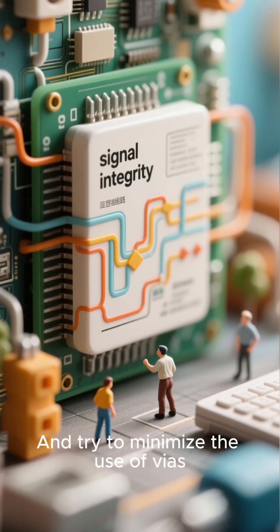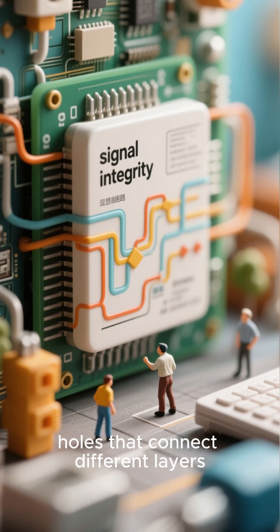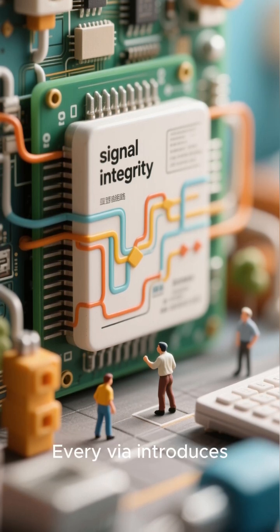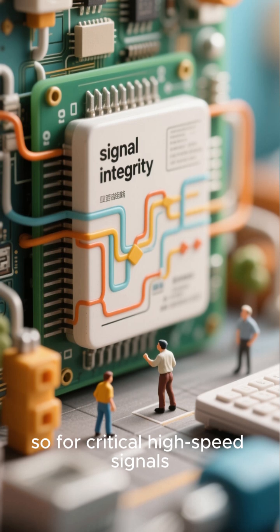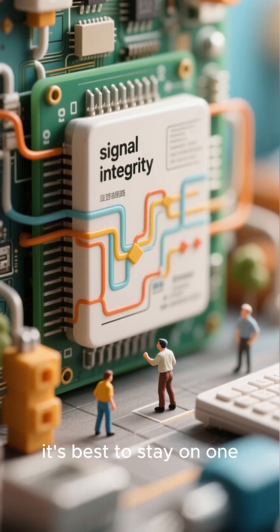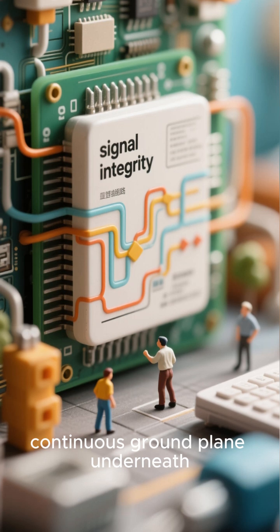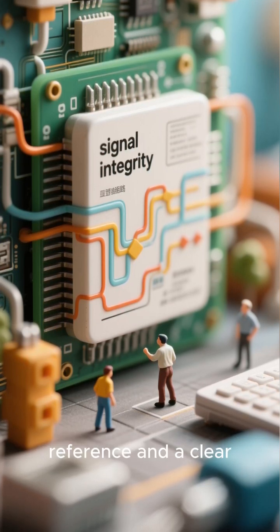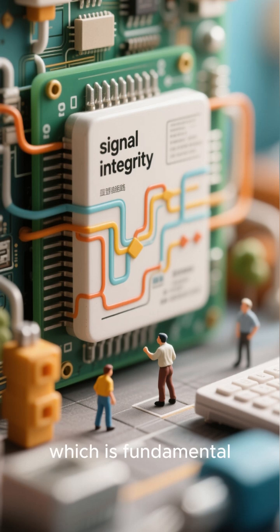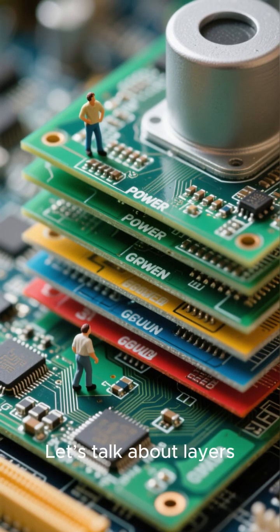And try to minimize the use of vias, which are the little holes that connect different layers. Every via introduces a small change in impedance, so for critical high-speed signals, it's best to stay on one layer as much as possible. A solid, continuous ground plane underneath your signals provides a stable reference and a clear return path, which is fundamental for good signal integrity. Let's talk about layers.